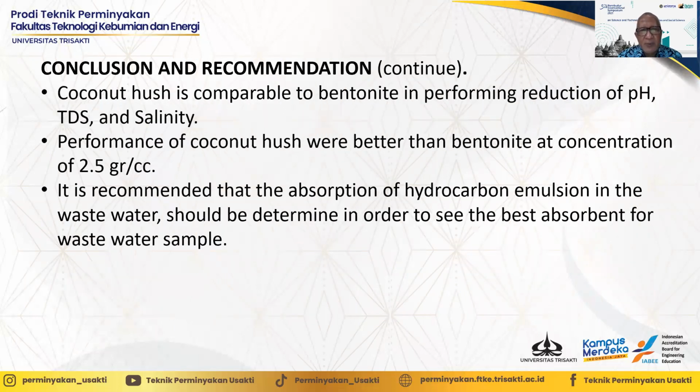Coconut husk is comparable to bentonite in performing reduction of pH, TDS, and salinity. The performance of coconut husk was better than bentonite at the concentration of 2.5 gram per cc. It is recommended that the adsorption of the hydrocarbon emulsion in the wastewater should be determined in order to see the best adsorbent for the wastewater sample.